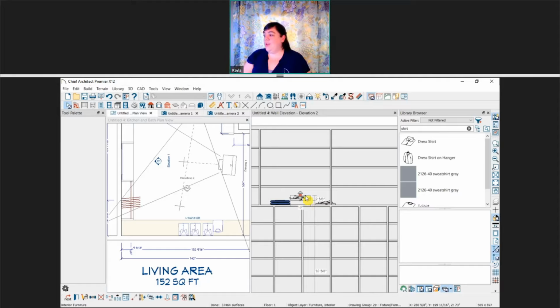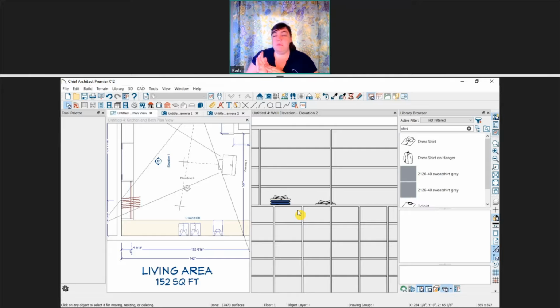And then I'm just holding down my control key. I don't know if I mentioned that earlier, but to free up all of my snaps and allow me to really easily move these around, hold down the control key, and I'll just place it right on top of itself. Elevation is absolutely how you want to do this. If you aren't in an elevation view, it's going to be much trickier because you're going to have to open each item and specify its floor to bottom separately.